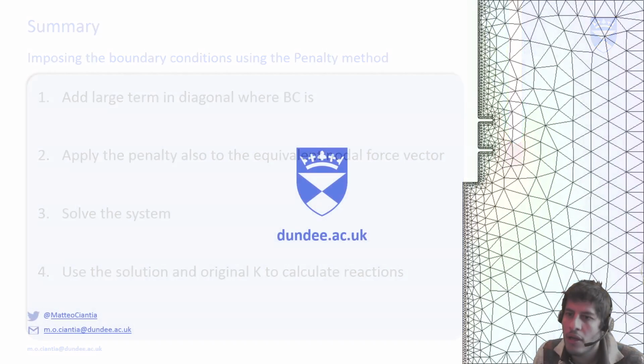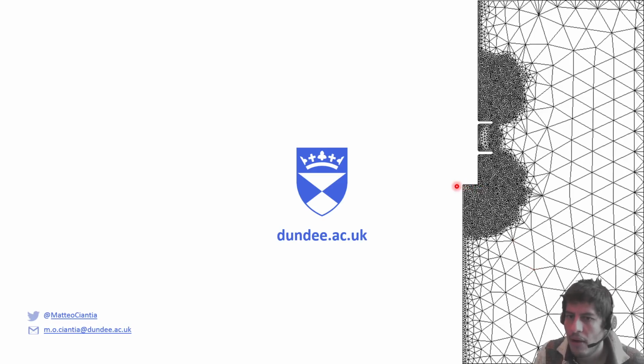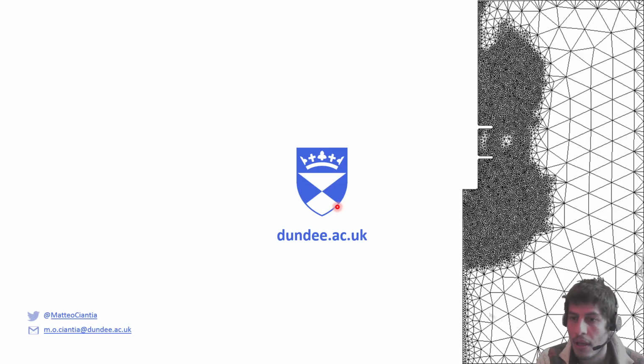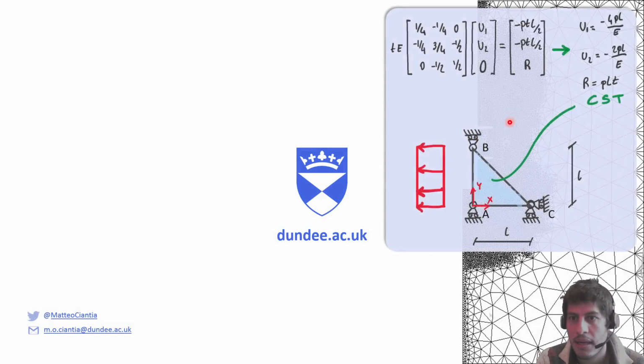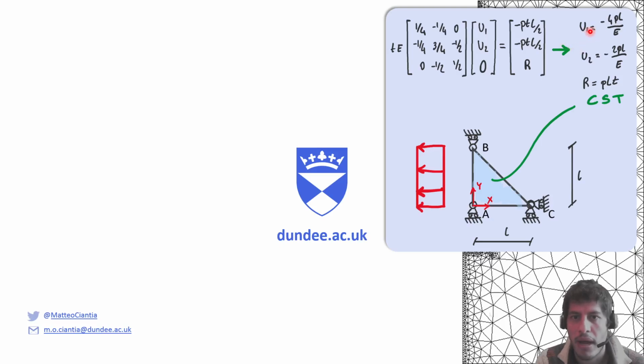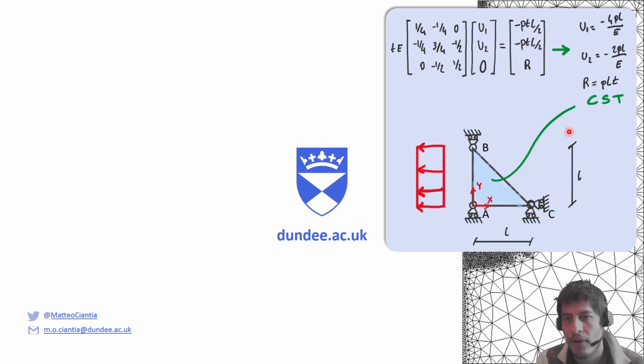Okay, so I will now show you in MATLAB how we can obtain the same result as last week. So this was the system that we solved. This is the solution. So U1 was minus 4PL over E, and U2 was minus 2PL over E, and the reaction was PL. Okay, and this is the problem to solve.